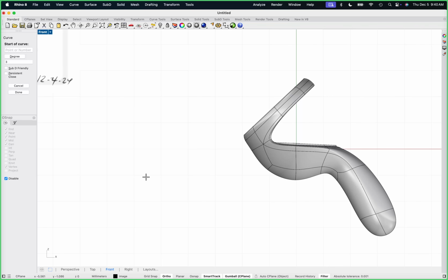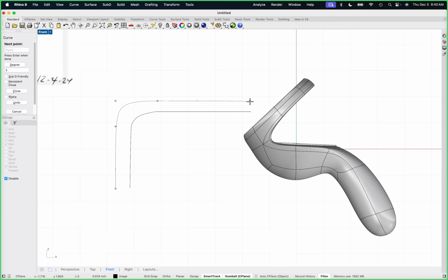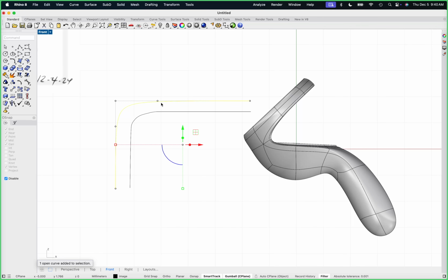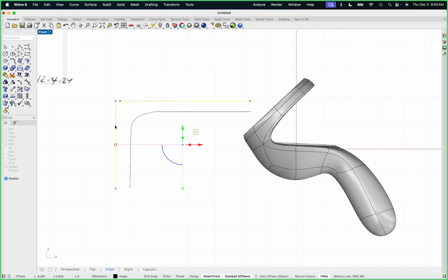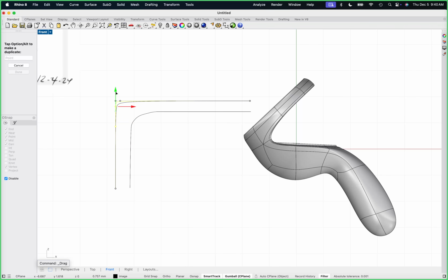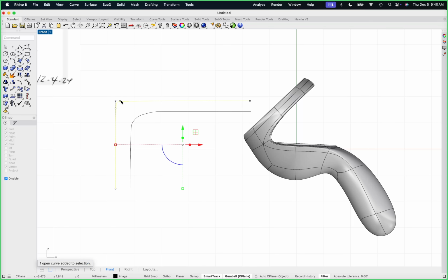When you draw a curve in NURBS, you don't make a corner like this. And if you do, stop it. You make a corner like this. Anchor point. 1, 2, 3. Anchor point. This is your corner, and if it needs to get sharper, you move these together. If it needs to get softer, you just move these farther apart.